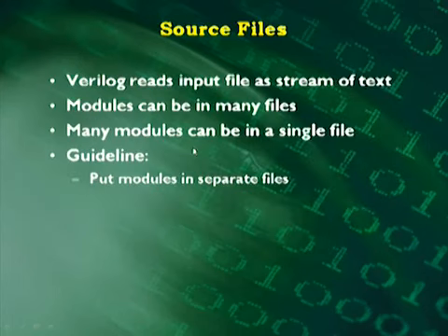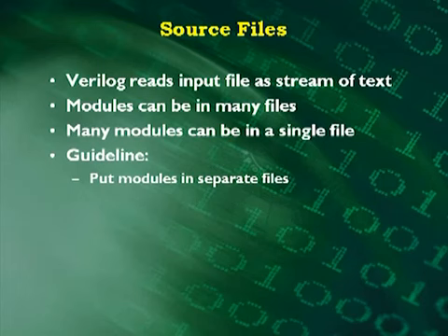Verilog reads the input files as a stream of text. And the modules can be in several different files. They don't just all have to be in the same file. In fact, you don't really want them in the same file. It's preferable that you put them in separate files.